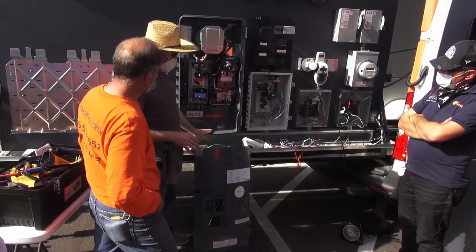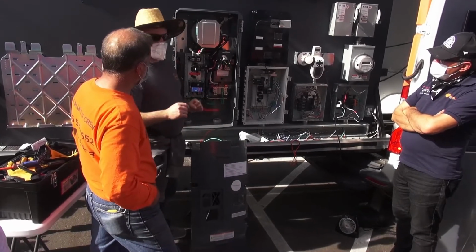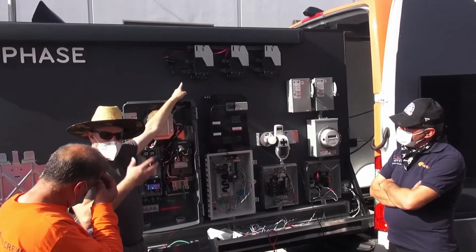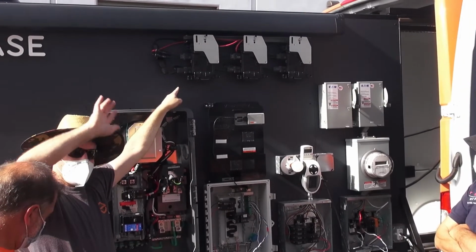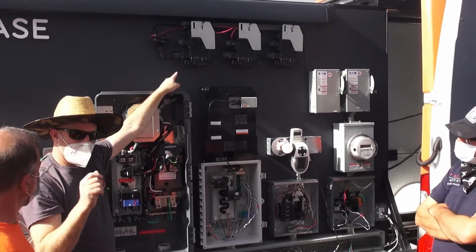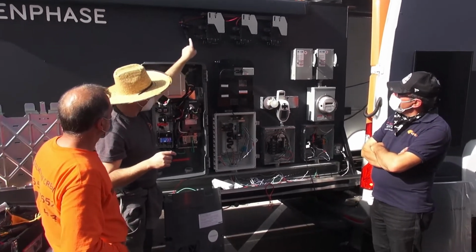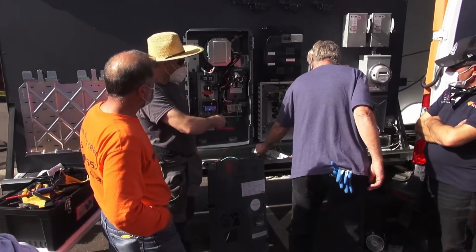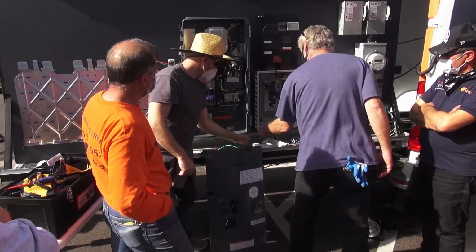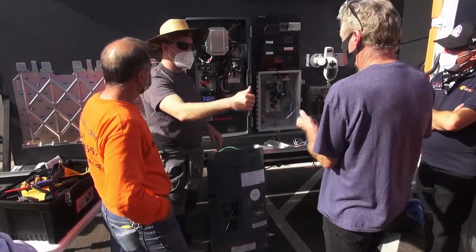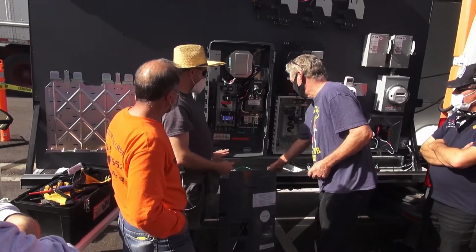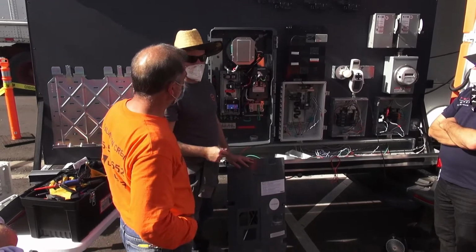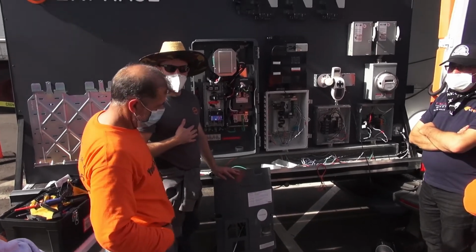So once you have System Controller 2, if you use IQ8 PV, which are the ones that can create a grid without batteries and without the utility, you have to have rapid shutdown. The reason is that circuit could stay live. You have to tell that circuit to shut off. So you have to add one of these switches. Now, if you put in IQ7s on a System Controller 2, it's up to you if you use a rapid shutdown switch or not. I think they're a good idea.